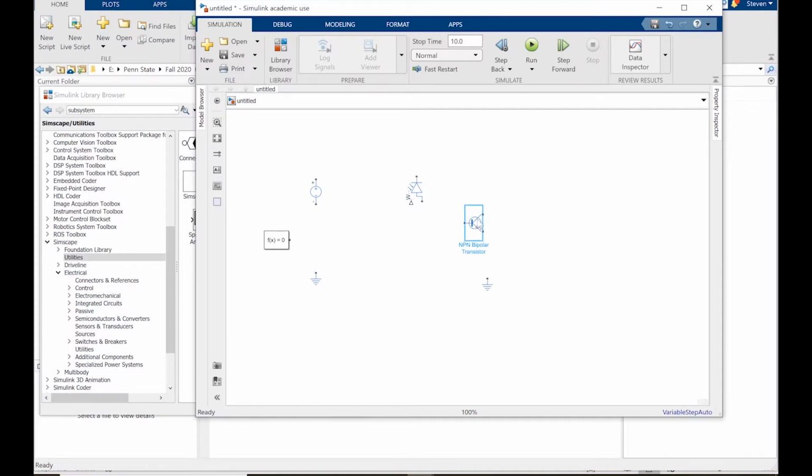All right, so the transistor is basically amplifying the signal. This is a physical signal input, and I just want to invert that, just because of how I want to arrange parts later. So this is basically the input. You can't really shine a flashlight onto the component like you would a real one. So we need a way to simulate the amount of light that's falling onto the photodiode. And this is what this input is.